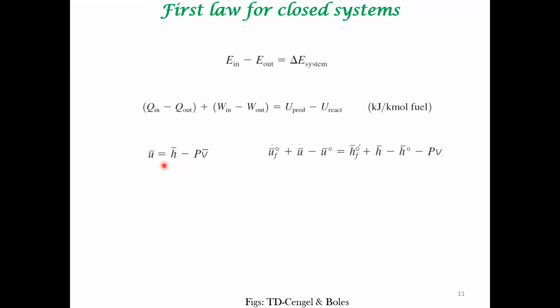So using the relationship between U and H, we can get the values of U, because H is what is in the standard tables. This is what is available to you. All the rest are fairly similar. You just plug in U in terms of these quantities and then present the formula. This is a computational formula that you utilize for making the first law balance for a closed system.